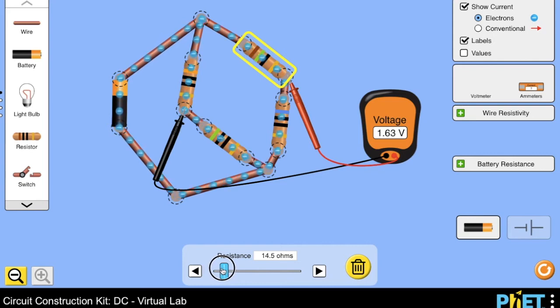If we keep looking at that voltmeter, we can see that the voltage difference is varying. So we are approaching 0. Alright, so we didn't get quite exactly to 0, but rather we got to negative 0.01. That implies that we need to change the resistance of either R1 or R2. So let's say we are going to be using 31 ohms for R1. So now we got exactly to 0.